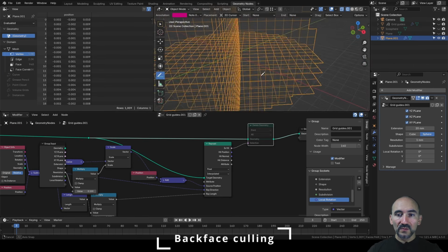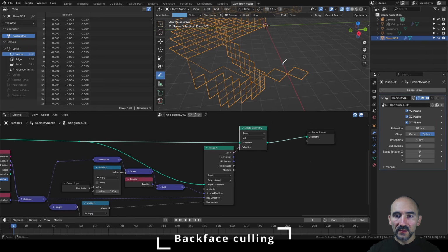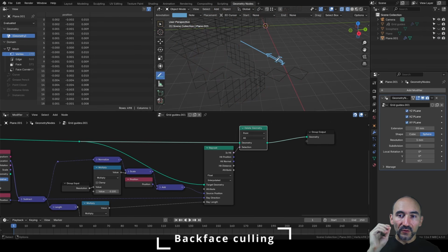As a recap, we are taking from each element the vector through the camera, we normalize the value, we scale the vector a little bit and move the position by a little distance through the camera. So for example here, from here starts the ray through the camera, and if this intersects the other part of the geometry, we have the hitting, and if we have the hitting, we can delete that point.